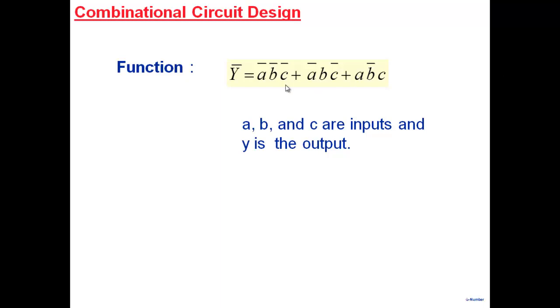Let's say, arbitrary example, you want to design an IC which has 3 inputs, A, B, C, and 1 output, Y. And the relationship between the output and the input is this logical expression here. All right, so this is the design that you want to carry out. So you want to make an IC. So the IC would have 3 inputs, 1 output, 4 pins, input-output pins, plus it will have a VDD pin and a ground pin. Right, so 4 plus 2, 6 pin IC. Right, very simple IC you want to design, and it should have this kind of a functional relationship.